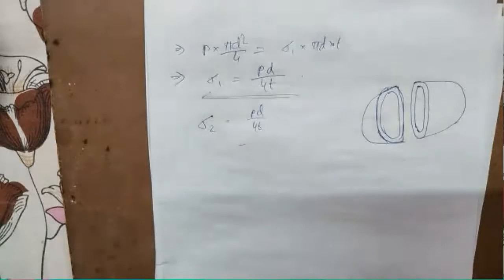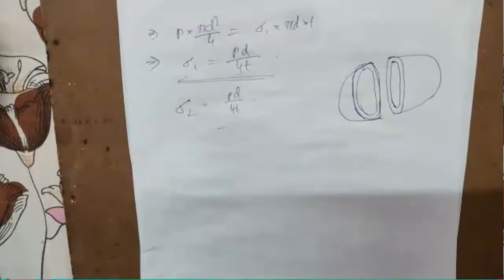So each point of the material will face two perpendicular, same value tensile stresses, both of them Pd by 4t.